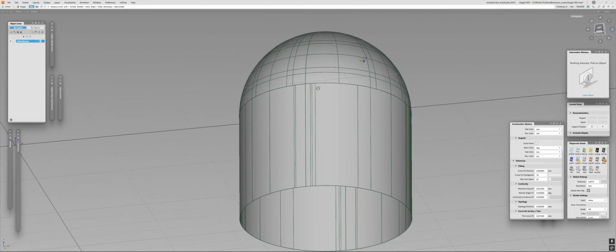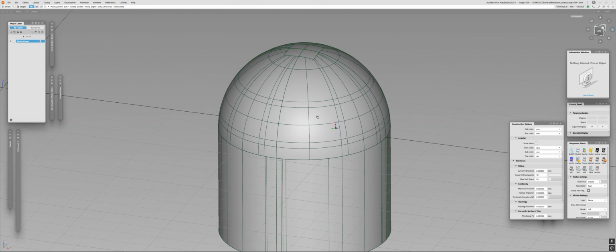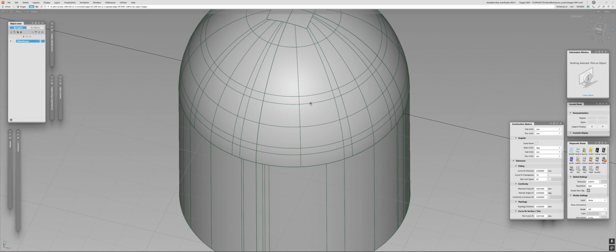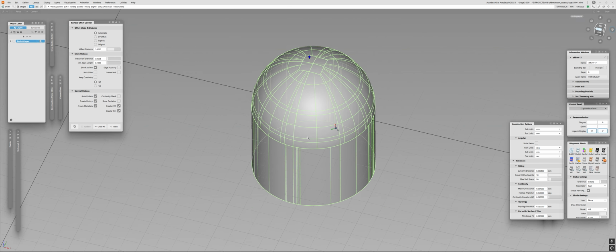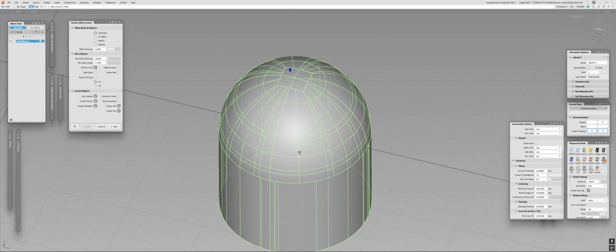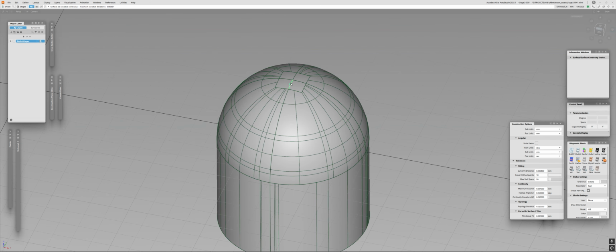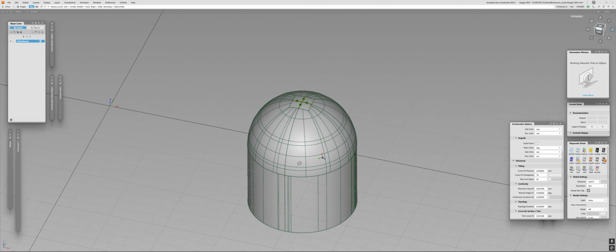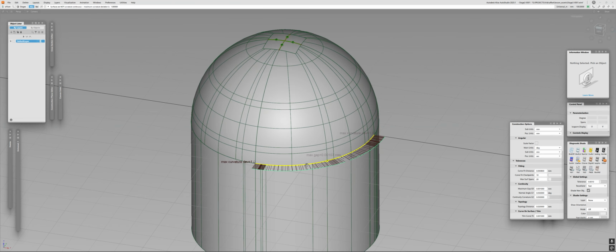So, what can you think about this? Well, what can I say about that? I can say that actually, from what offset is, Alias did a pretty good job. It took my additional surfaces into consideration. It maintained my trimmed edges pretty well, even though they are very biased. So in this regard, this is quite nice. It even got all the curvature in between, which is even an overkill, but it wasn't able to maintain a gap here.